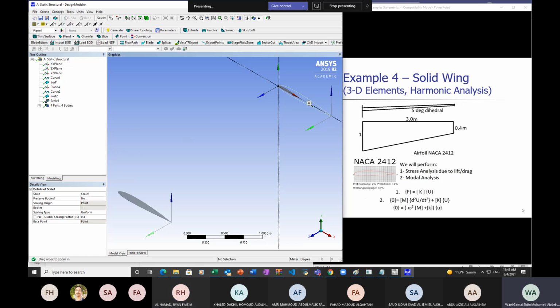Okay, now we need to create the plane. So the plane on the other end. So if you click here, create new plane. When you click a new plane, you choose in the transformation below where you want to create it. Choose from the side here offset z, because I want to do the transformation in this direction. Offset z -3. Did you do this?